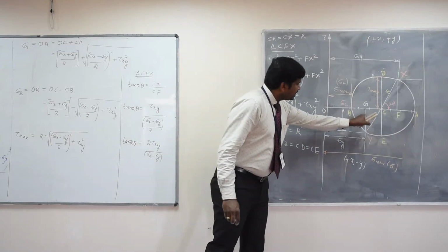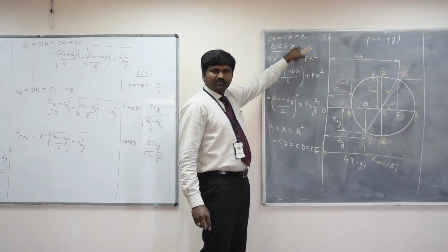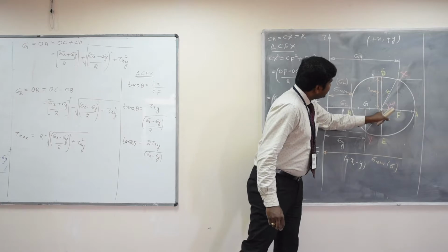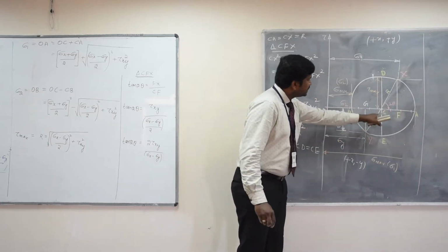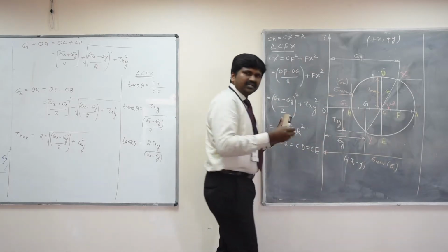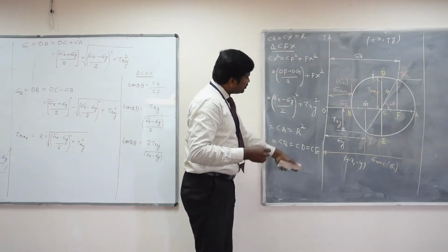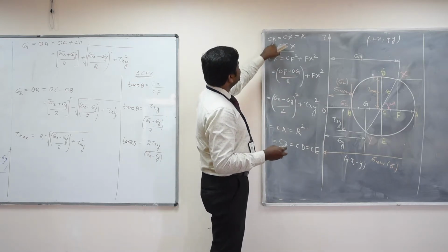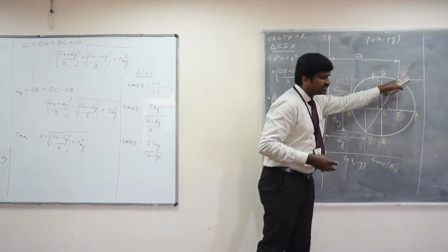From this Mohr circle diagram, you should be able to calculate the radius of a Mohr circle. Please remember, the radius of a Mohr circle gives the maximum shear stress. That means CD, CX, CY, CA, CB, all are giving you the radius of a Mohr circle. Now, how can we find the radius of a Mohr circle? We already know that the radius of a Mohr circle is equal to tau max. But how do we prove it geometrically using this equation? So let us see. We know CA is equal to CX is equal to R. All are radius.